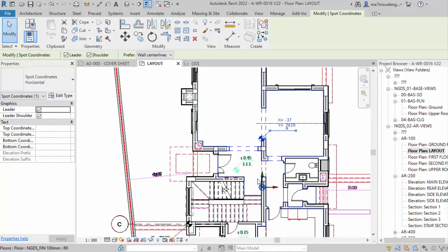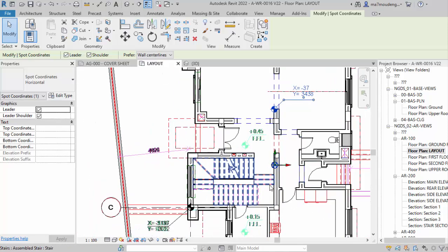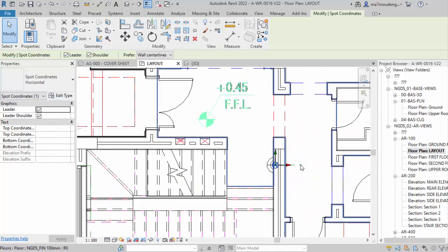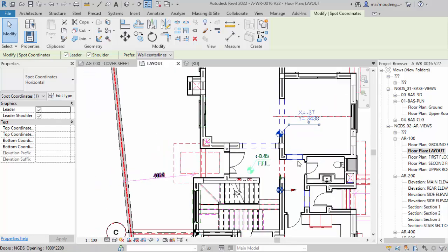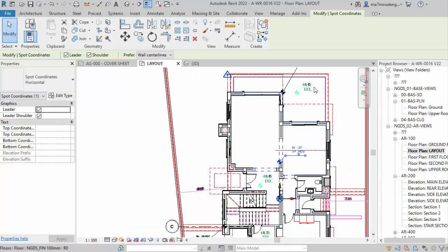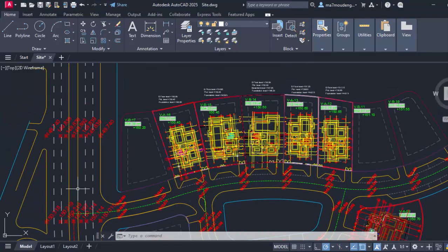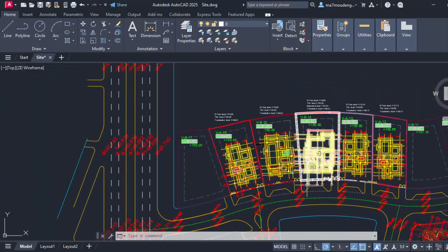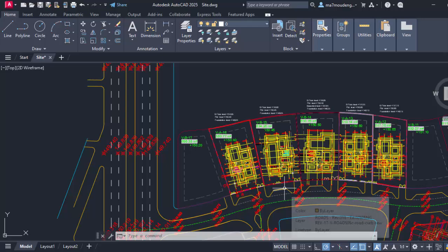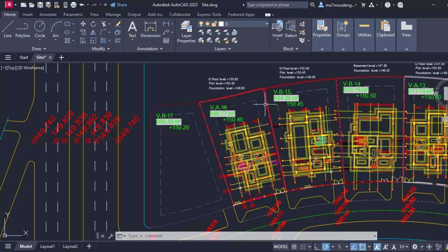As I told you, there's another option, which is to make the internal origin a known physical point in your project. So right now we know that we can use the project base point as an origin point for your coordinate system, but only for this project or this building. For example, if this is my layout with many buildings, and each building is a separate Revit project or a separate Revit file, and in each one there are multiple disciplines: structural, architectural, mechanical, and so on.